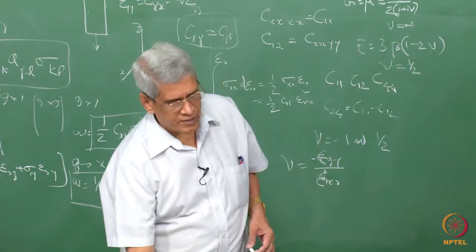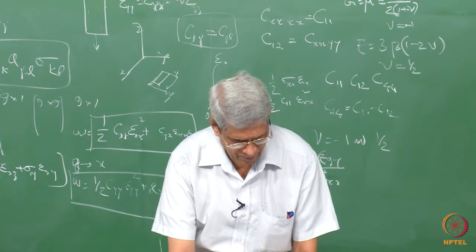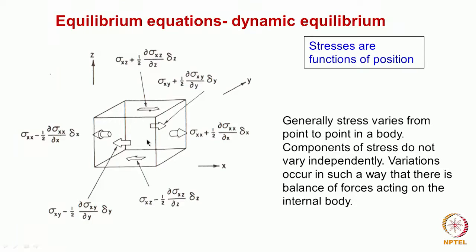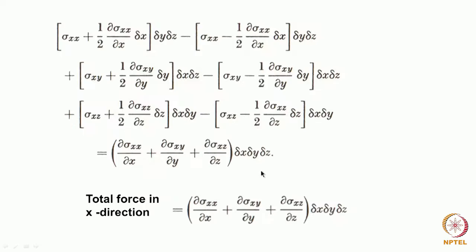Similarly, shear stresses are also going to act. The shear stress is on this y surface. If you consider it, we have a stress which is going to act in this direction, and similarly this is the stress which is going to act in this particular direction. So there is going to be a net force which is going to act on this y surface, but in the x direction. Similarly, on the z surface, also in the x direction, there is going to be a net force.